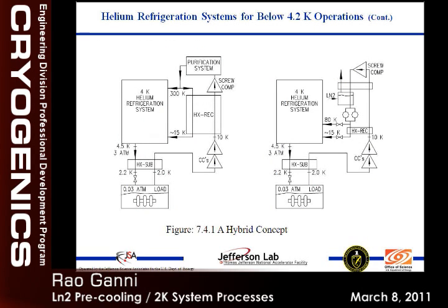So when it comes to that, these use 2, maybe 3 sometimes, to raise this pressure to anywhere from 0.2 to 0.4 atmosphere. So the pressure drop influence is less, and you still have subatmospheric operation. But you can approach the screw compressor level instead of the vacuum compressors at that pressure level. And you can have various arrangements to get there. It will give you the pump down easily, because you can use this compressor to get it down to 0.2 atmospheres before you start these cold compressors. That makes it much easier to pump it down from there.